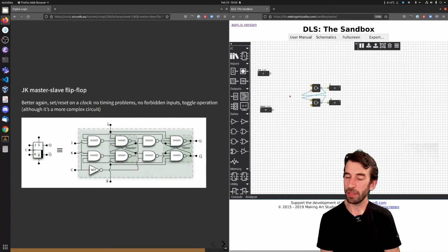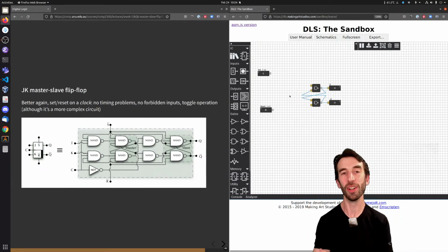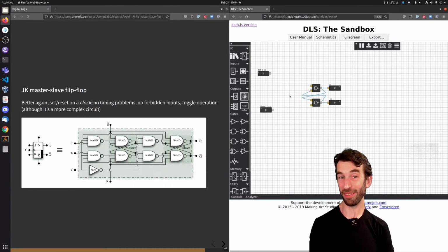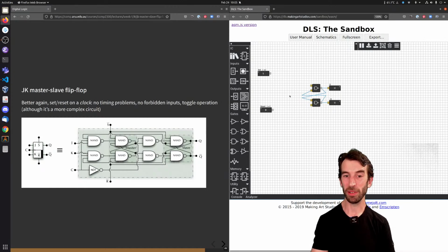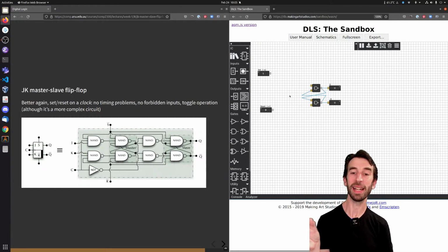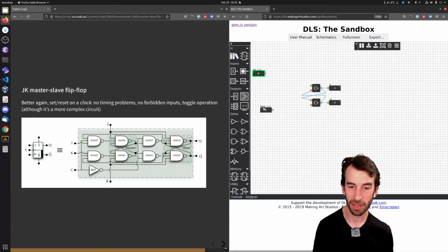So the 0, 0 input, it's got this forbidden term, like you're not going to go to jail if you set an SR circuit to 0, 0. In fact, I did right in front of you. The only thing that's bad about it is if you expect to know what the output will be if you then go to 1, 1. So 0, 0 to 1, 1, you just don't know what the output's going to be. So if you turn off your device, you have to initialize it, set it into a known state by putting 1, 0 input or 0, 1. And then it will be in a known state after that. The unknown part is only going to affect us if we...